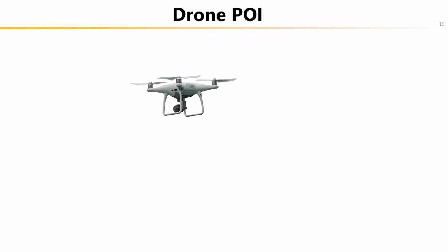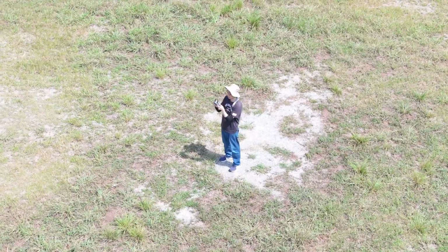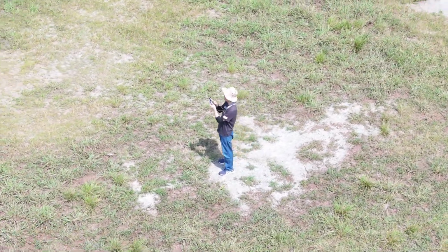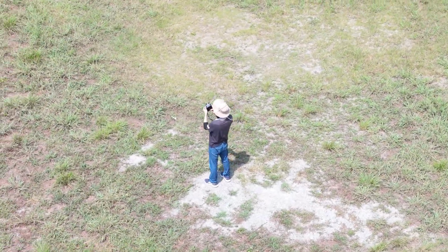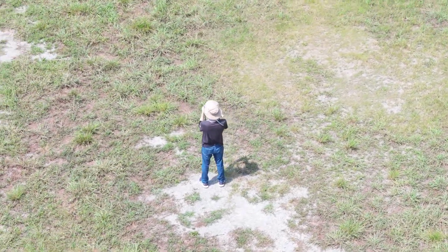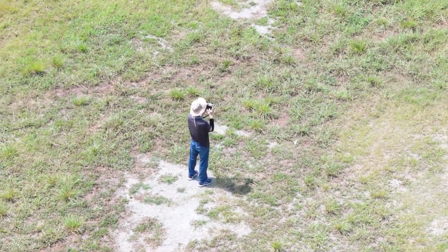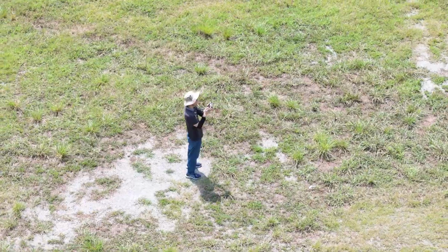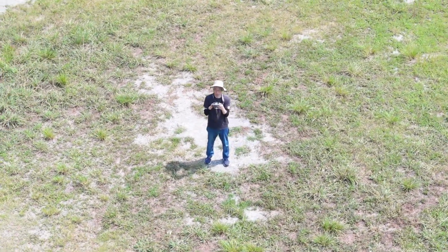3D modeling using video footage of a drone performing a point of interest orbit will be performed. In this video, a person is standing in a field, and the person is the subject. Due to the approximately 46-second recording time, the sampling frequency of 3DF Zephyr was set to 50 frames divided by 46 seconds, which nearly equals 1.1 fps. The results are shown below.